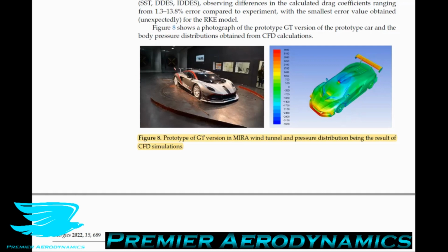So in other words, they've gone into the experimental wind tunnel, they've looked at the drag and the lift that they're getting, with errors of about 3.8% to 6.5%. They're also looking at the CFD that they're using, whether they're using RANS with whatever turbulence model, plus more high fidelity ones, DDES, IDDES. I should probably cover these in a second.